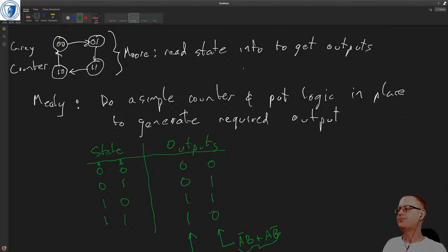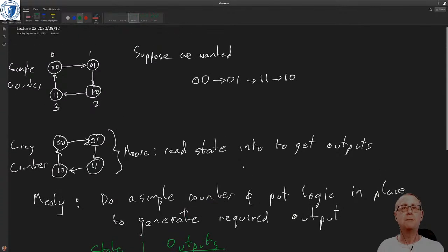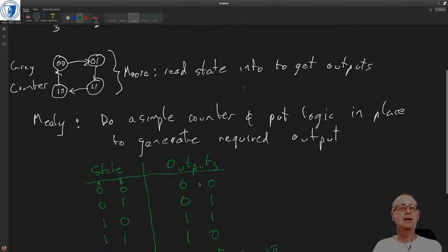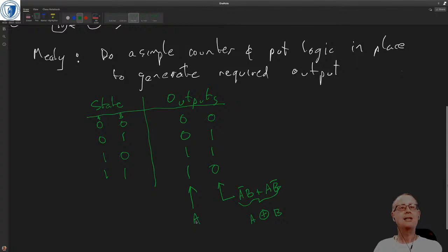Okay. And all that's in the next couple of slides is a slightly more complicated version of that. I thought it might be easier to come to grips with a smaller version, just a modulo 4 counter. Obviously A is really easy to get, and we do need an exclusive OR gate for the other output, but that is also pretty simple to get.